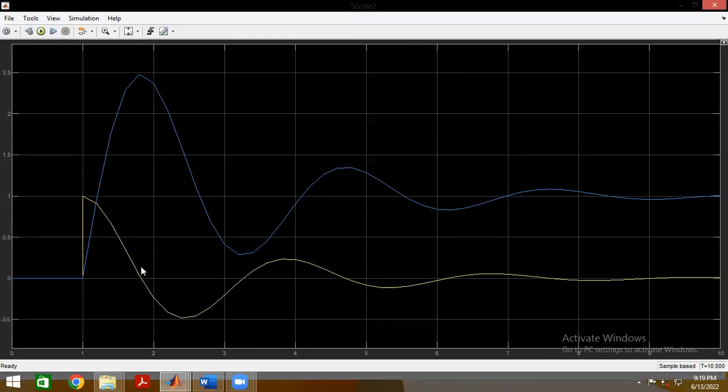So if you then look at the blue curve, we are giving the highest input or the highest driving signal to the plant right at the 0 crossing, because this is where our area is at its largest. And because our area is at its largest here, we need to drive that plant as hard as we can so that we reduce this area. And this is what causes the error to go negative, because we've essentially overdriven that plant. And now it becomes negative.